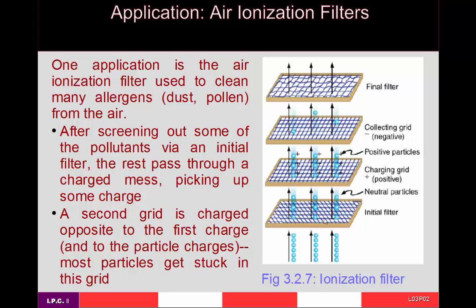That's pretty good, but if you start with, let's say, 100,000 particles per cubic meter, then you actually have pretty clean air already. In fact, they make clean rooms that have a 100,000 rating. But by removing 85%, you're still left with 15,000 particles per cubic meter.